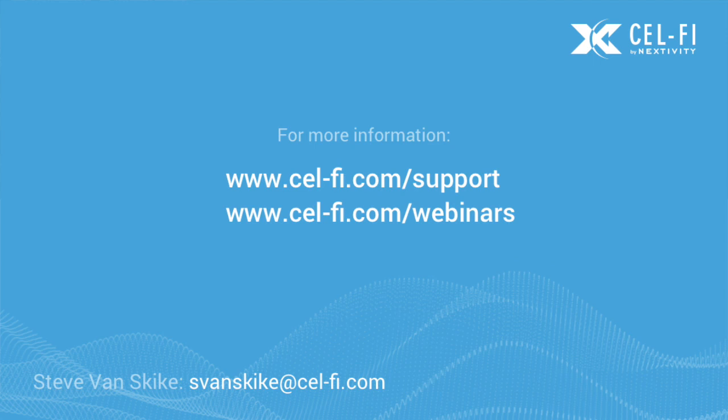If you use the LPDA, it's usually for 2 operators and you'll need to sum those. So it takes a little more hardware because you would need a splitter or a hybrid combiner if you have 2 LPDAs going in different directions. But if you have to do that, then you really need to do that. But for most cases, the MIMO panel antenna is probably the one that ends up being the most used.